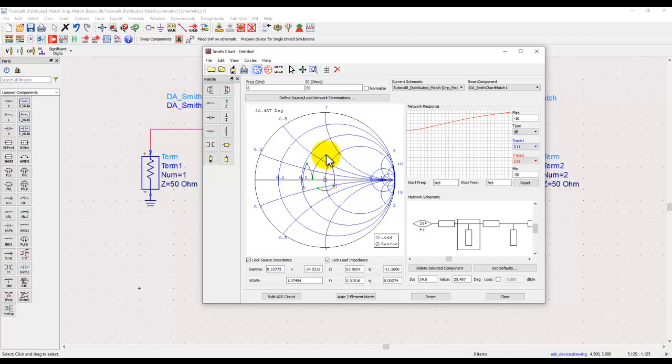And again, you can start playing with impedances a little bit. For example, if I make this impedance a little high, for example 70 ohm, again depending upon how much width you are going to need, then you will have that point crossing the unity point. And now you have a similar kind of matching network here. So now you fulfill all the criteria.